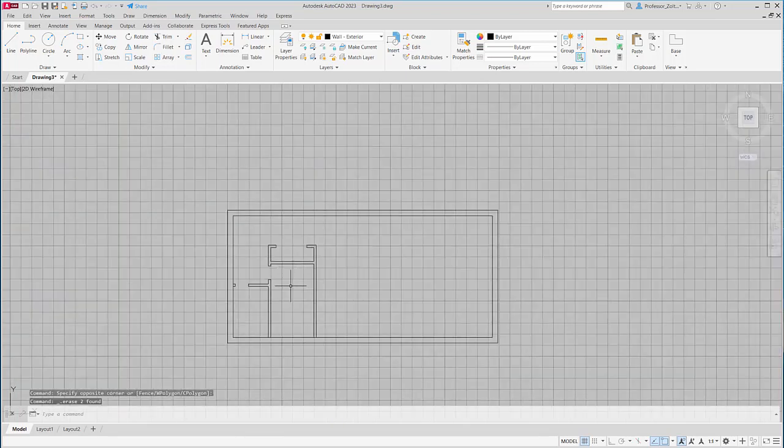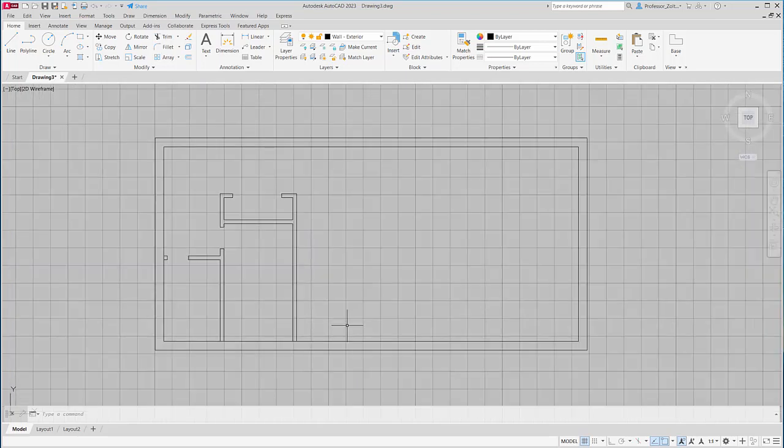Okay, so I've shown you a couple techniques here. You have to complete your drawing, all the walls, using this technique. And the idea behind the repetition is to help you become coordinated with using offset, trim, the values you're putting in, where the numbers come from, and putting it all together. So today's lesson was basically just on layers, working with lines, working with construction lines, working with trim, modifying this to look exactly like the layout that you have for your project.